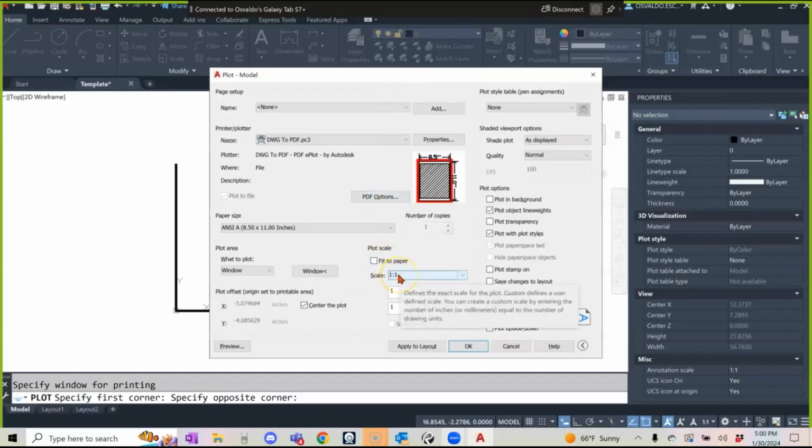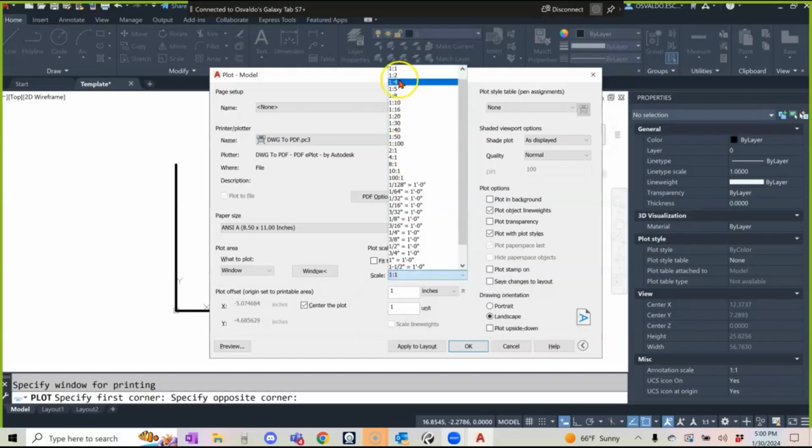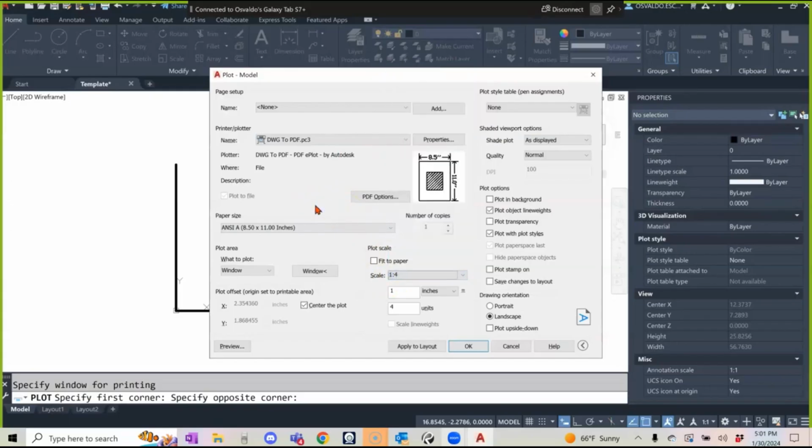As soon as I do 1:1, you guys will notice that my border became red. That is, my drawing that I just drew is too big. I gotta shrink it. Let's do 1:2. Still too big. 1:5. It's too small. Seems to me 1:4 will be the nice one. Yep, so 1:4. Actually, we'll give you a little preview of how it's going to look once it's printed.